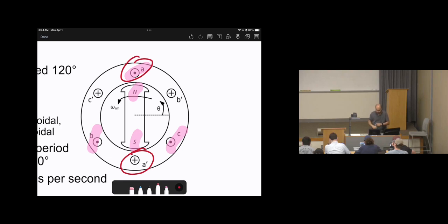So we see that there is A bar, B bar, C bar, because these are based on three-phase. Then there is a magnet, with north and south poles, and that magnet is rotating. Since the magnet is rotating, there is movement and there is a magnetic field. According to Faraday's law, the voltage will be induced in the coils at A, B, C.